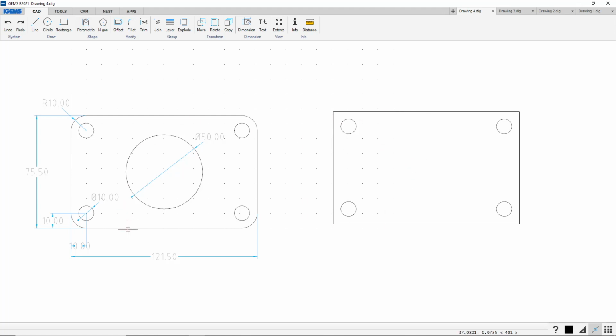And the fillet is radius 10, so fillet, predefined value is 10, looks good. I click on it, and then polyline, I select this. And now we have to put a circle.